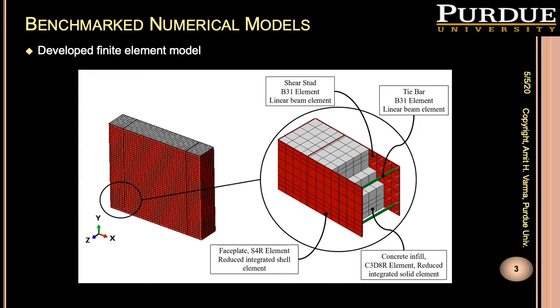Three-dimensional thermal and stress finite element models were developed in Abaqus. The developed models were based on sequentially coupled thermal and stress analysis within the finite element software. The temperatures of the nodes were obtained from the thermal analysis, and then the nodal temperatures were used as an input in the stress models.